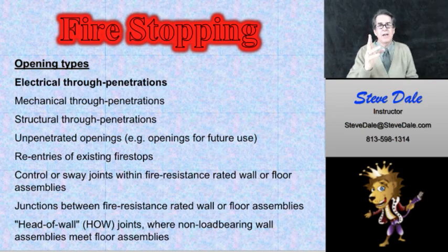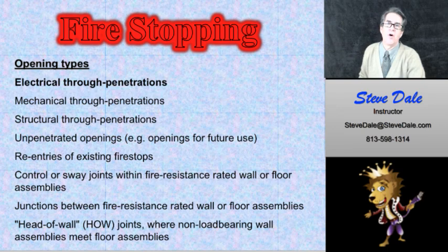It could be cement. There are mechanical fire stops and non-mechanical fire stops. A mechanical fire stop is actually a mechanical device that you put the wires in. It's got fire stop material in there, and you lock it down on the wires. Usually they're expensive, and they usually use them for a lot of cables. Non-mechanical would be some kind of cementitious material, maybe a putty, not just regular putty or regular caulking. It has to be rated fire stop material. So that's all you really need to know about that.